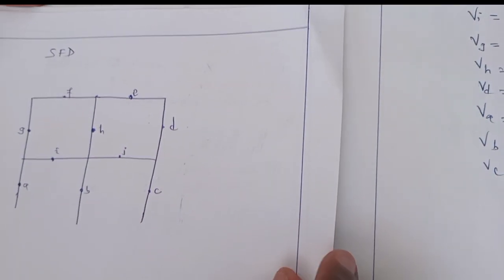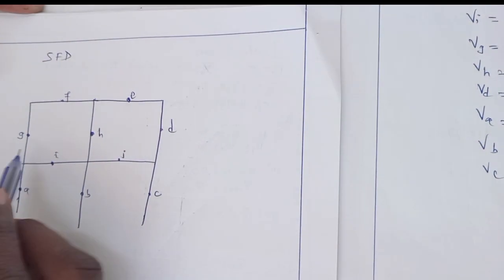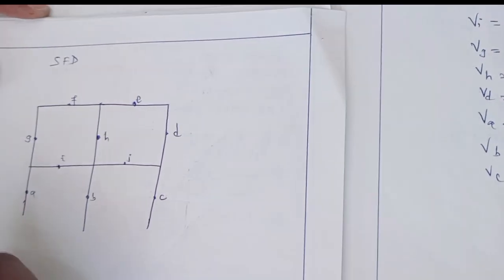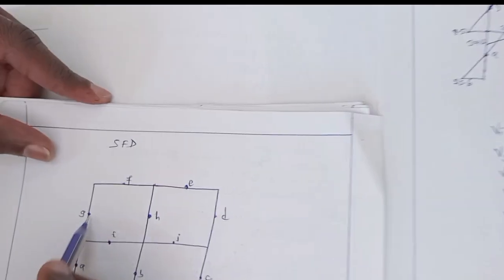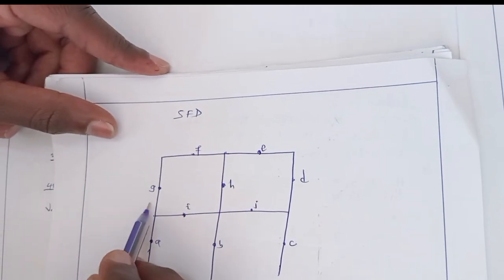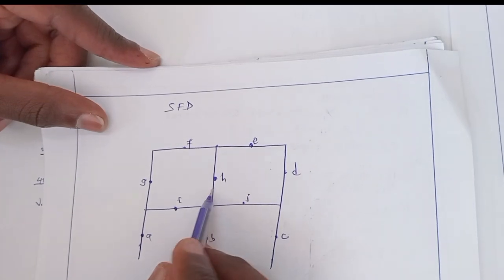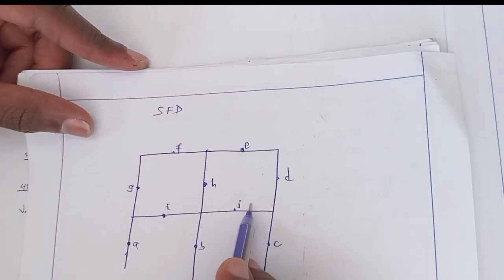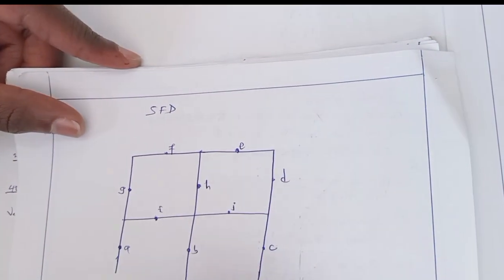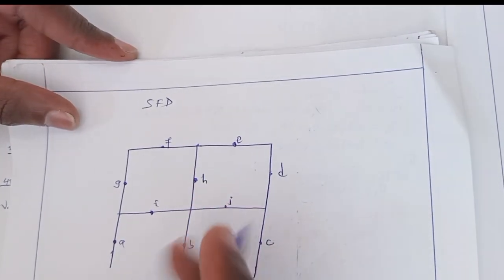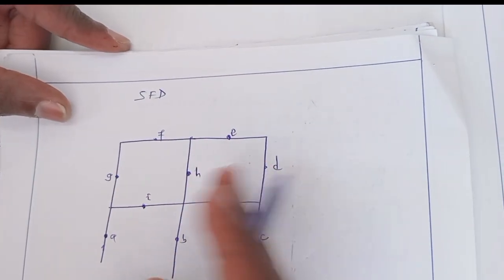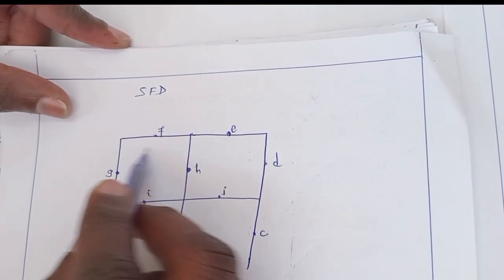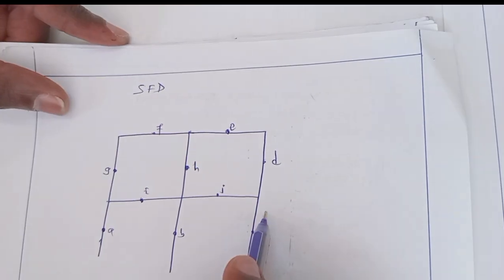During drawing the shear force diagram, the case to consider is you choose which side will be positive for each member. Since the shear forces are all positive, even for horizontal members, we can select this region to be positive, and downward also positive.